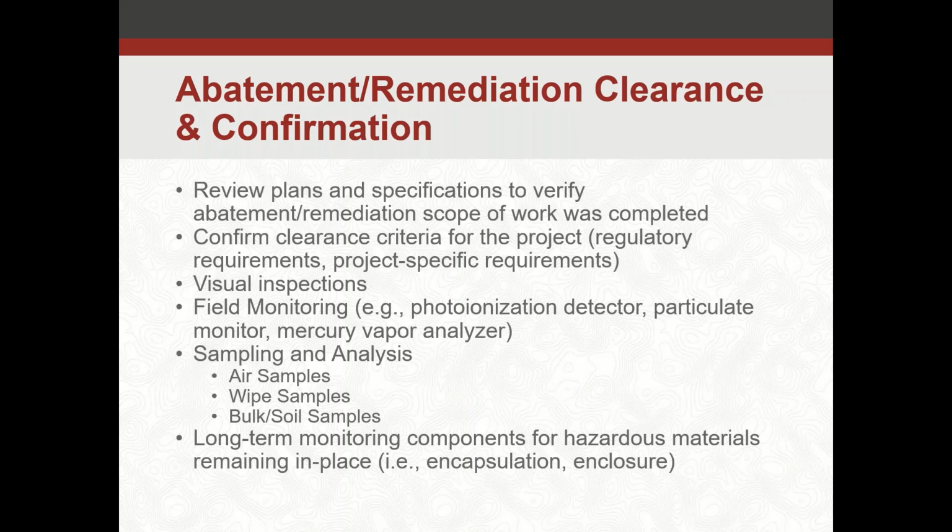When we do the monitoring, you're going to have an abatement clearance confirmation. You're going to want to review your plans and specifications, making sure the work was done in accordance with the requirements. You want to confirm the clearance criteria, whether it's a regulatory requirement or a project-specific requirement. A lot of times you're always going to have a visual inspection. You want to make sure you're not seeing the issue anymore.